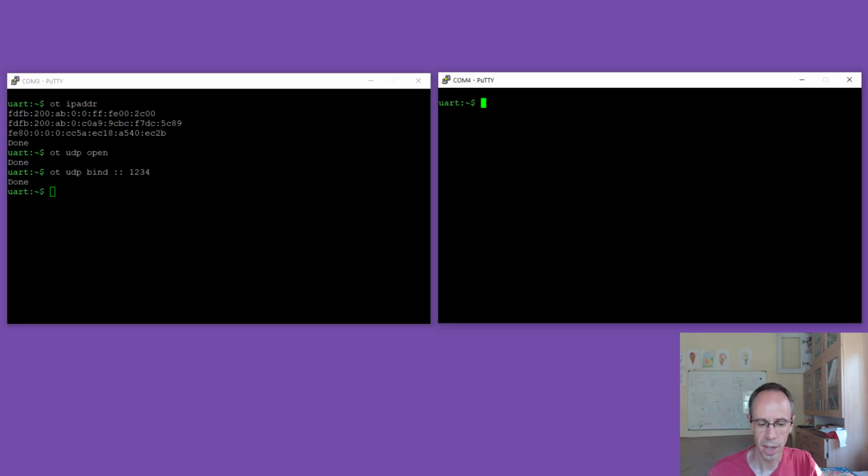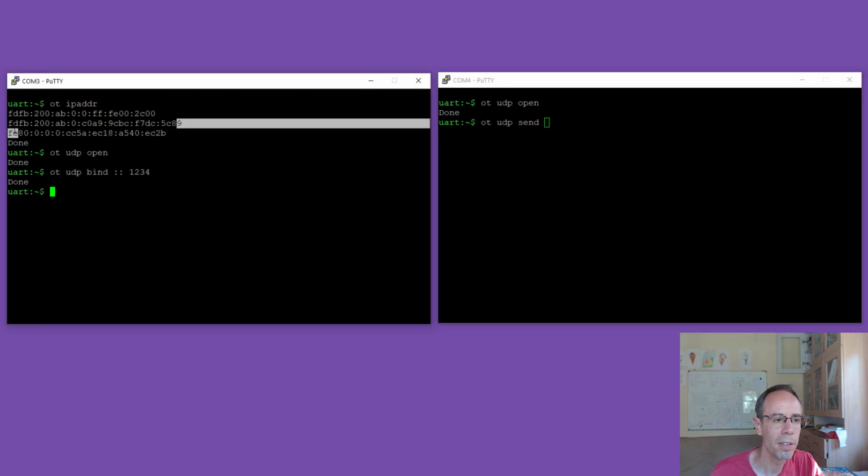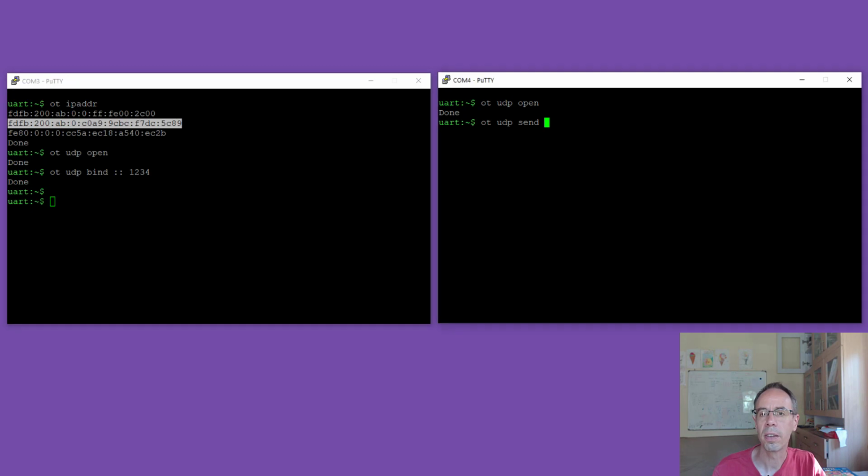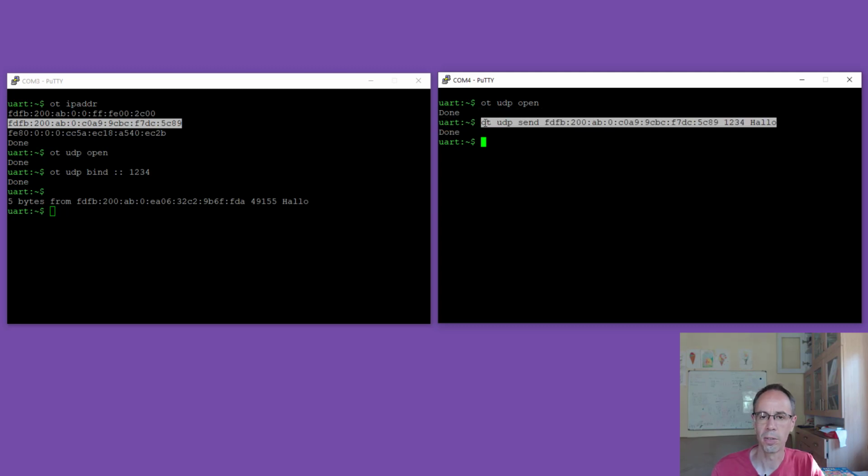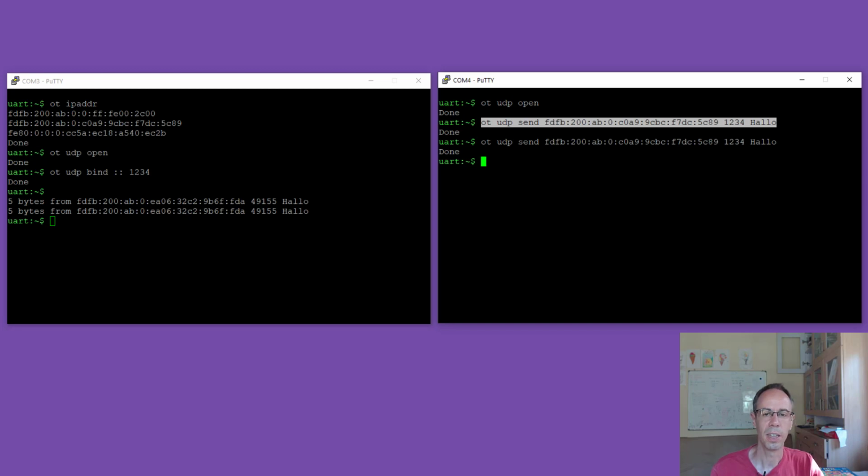And on the second device now we open UDP. OT UDP send. Now we have to copy the IP address here. This is always a little difficult. So, copy. Then we put it here inside. Send 1234. And send the text hello. And we're seeing that this message arrived here. When we do it again, it will also happen again. So we're seeing we can successfully transfer a UDP packet.